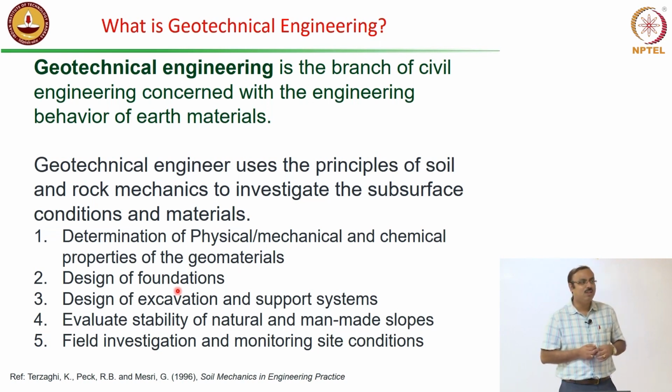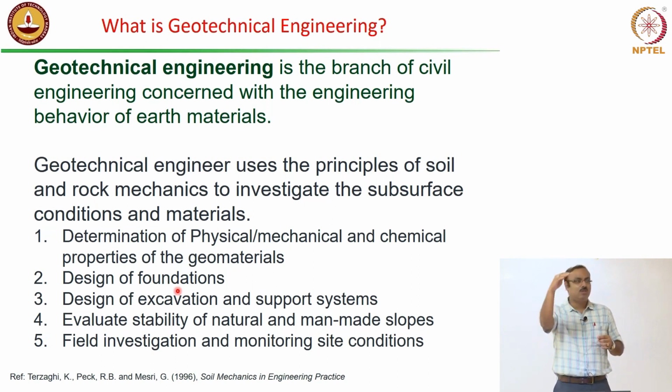So, same thing stands for all the geotechnical structures, even more actually. We do something, we protect the slope, we have designed the foundation with marvelous accuracy and engineering sense, but unless you monitor the performance continuously, you may end up losing the design life. So, let us say a particular tunnel is designed for a design life of say 100 years, unless you continuously monitor whether there is any water seepage going on inside, is there some part of the shotcrete, that means the surface of the tunnel, getting deteriorated. All this will tell you what is the health, what is the condition, just like our health, the condition of the tunnels, or the same thing applies for the bridge foundations or regular foundations.